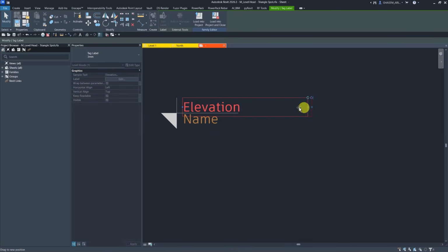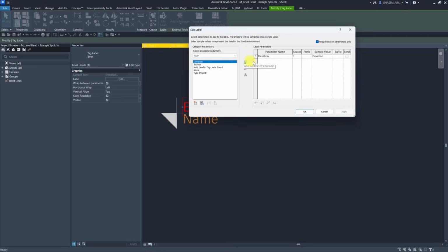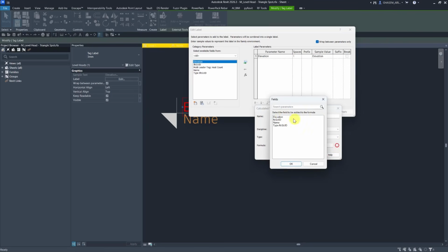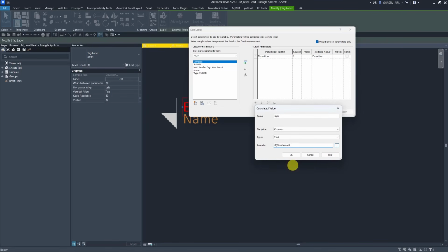Then maybe minimizing the frame. And I can also specify a formula here for displaying the mathematical symbols automatically. So symbol, type text. Then as for the formula, if inside open parentheses, the elevation was equal to 0, comma, double quotation, hold Alt and type down 0177.